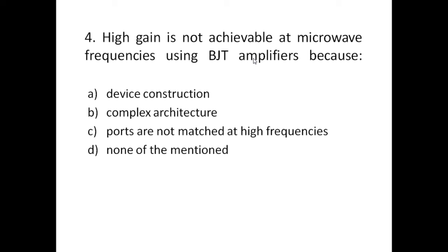But when the frequency starts to increase, that port will be unmatched. So due to that, we won't achieve high gain at microwave range frequencies. So the answer is ports are not matched at high frequencies.